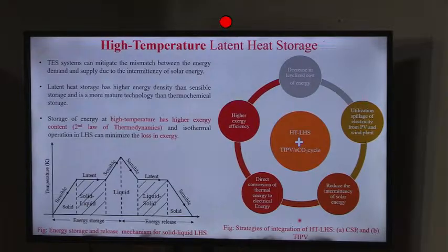If I'm speaking about the second law of thermodynamics, there is a concept known as the dead state. What is that dead state? Dead state is that state when your system is at its minimum potential or minimum energy. Like it should be at, say, room temperature. It should not have any sort of activation energy in it, but still it is having some energy which you can't extract. So that is the dead state.